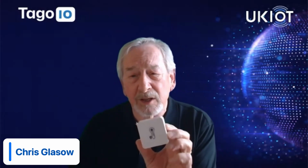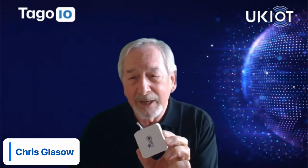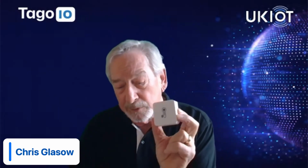We use a standard type sensor with an external antenna wherever we can. If we have to, where we have nice, smart internal buildings and rooms that need to look very cosmetic, then you need to go for the monopole spring. So that's the first thing. Remember, an external antenna gives you all the link budget that you paid for. That's my first advice in terms of sensor selection.